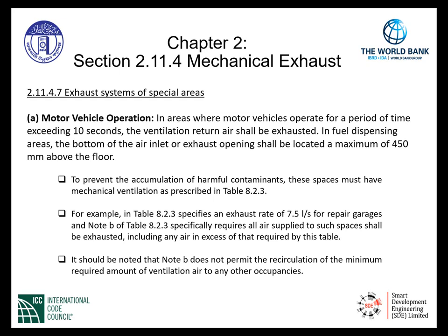However, in fuel dispensing areas, the bottom of the air inlet or exhaust opening shall be located a maximum of 450 millimeters above the floor. Now, this is to prevent the accumulation of harmful contaminants.